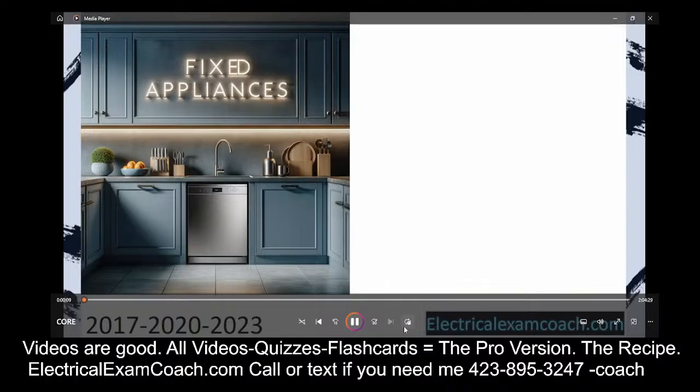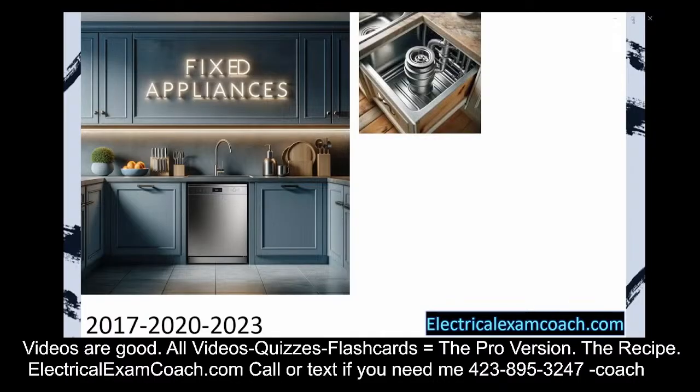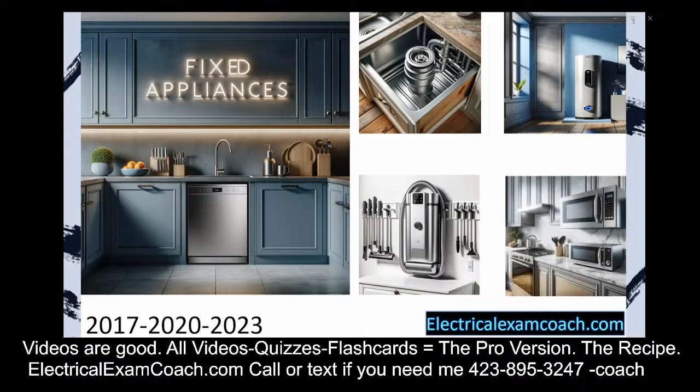Today we're going to be learning about fixed appliances and how they work into a whole house load calculation. Fixed appliances include things like dishwashers in this picture, but it also includes things like garbage disposals, water heaters, central vacuum systems, and microwaves, and pretty much any other appliance once it's fixed. You'll notice in this bottom right-hand picture that there's two microwaves. One is not fixed, and the other one is fixed.